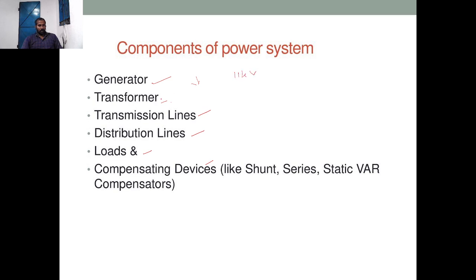If I want to transmit that power over a long distance, I cannot simply transfer it at a low voltage level, because the losses will be greater. To reduce the losses, I have to step up the voltage level. For that I use a transformer, and with its help I can step up the generator voltage to a higher level.